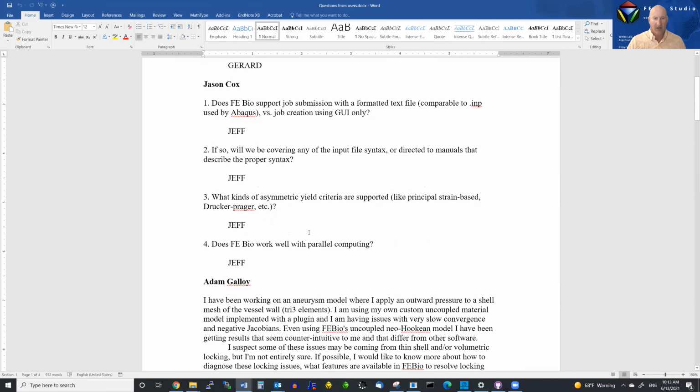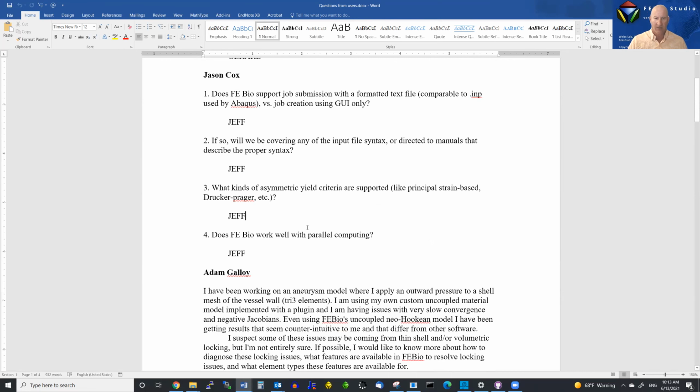Okay, so this next one is probably a question for Gerard, because it refers to plasticity materials in FEBio. If I remember correctly, the manuscript for the reactive plasticity capability is still under review. Is that correct, Gerard? Yes, it's been an endless review. It's been a tough review. However, the quick answer is we have the von Mises yield criterion, and we have the Drucker criterion. We don't have Drucker-Prager, but those are easy to add.